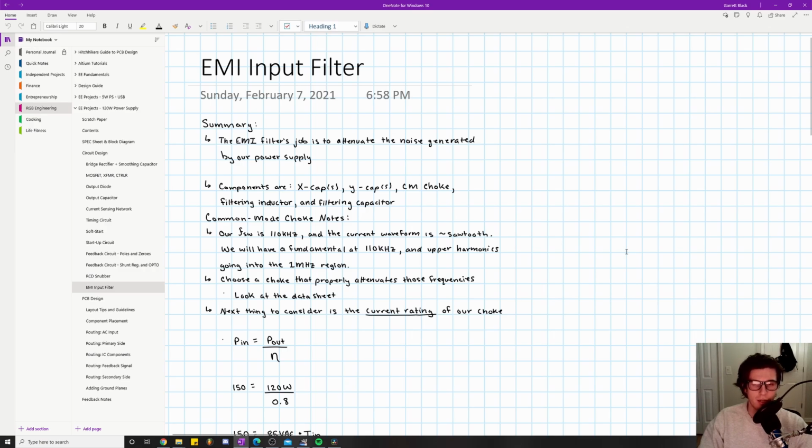If it doesn't, go back and watch the previous videos I made. Hopefully that'll answer your questions. If it still doesn't, drop a comment down below, and I'll be happy to make more videos talking about it. But just know that we're trying to deal with a switching frequency of 110 kilohertz. So what we're going to do is choose a choke that properly attenuates those frequencies.